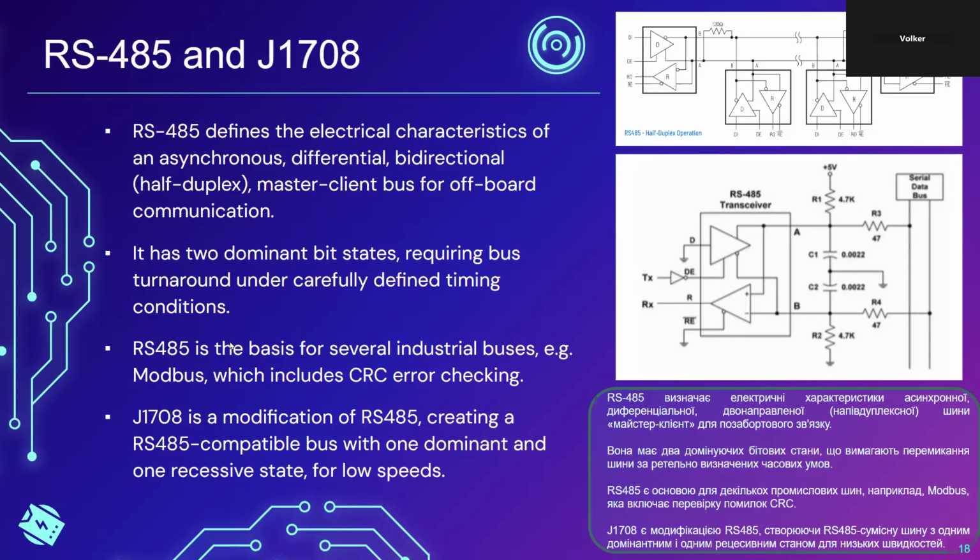It has a differential signal line, so it operates in signal pairs. It uses 2 lines, but the signals are also ground referenced. Sometimes I see people not connecting the grounds, and often this works because the differential drivers that you can purchase, the RS-485 transceivers, are pretty good.